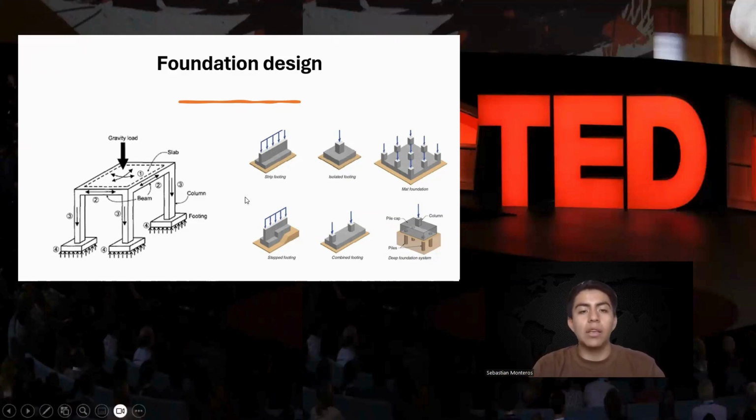Talking about foundation design, we determine it based on the geotechnical study. As we can see in the image, we have a lot of foundation designs, like the isolated footing, the combined footing, and the mat foundation. That is going to depend, again, on the geotechnical study, but also on the characteristics of the structure, like its weight and design.